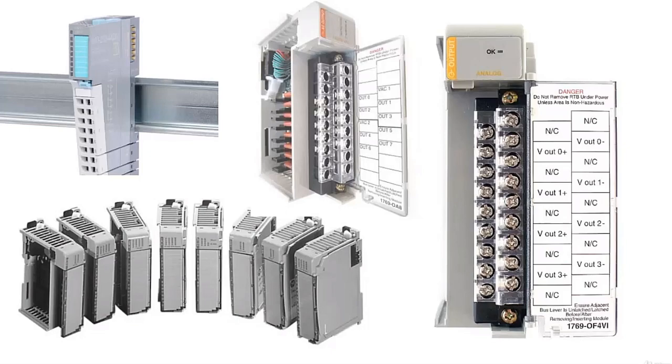And the modules come in all different shapes and sizes depending on the type of PLC and the manufacturer that is behind it. And there are very general modules that handle simple digital inputs and digital outputs, and there are also some more specialized modules specifically geared to RTD signals, thermocouple signals, high-speed inputs that have to be read at a much higher frequency than a typical module can handle.